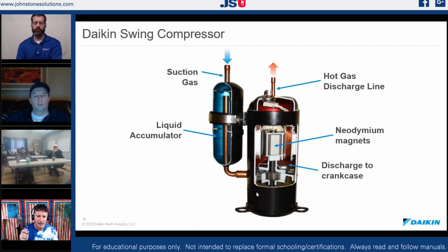And if we look at the function of a rotary compressor, there's some things to point out that don't always get talked about. If we read a Goodman installation manual from 10 years ago, when it was primarily reciprocating compressors, the installation manual itself actually instructed you to open the suction valve on new installations first to balance the pressures in your system. When we talk about these style of compressors, we have to really think differently about that.